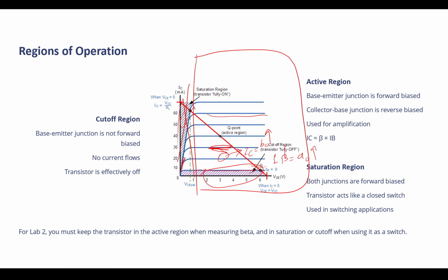Is that clear? So when you want to analyze it, don't run KVL. Find out what the base current is. The current through the collector and emitter is going to be the coefficient times that current of the base.